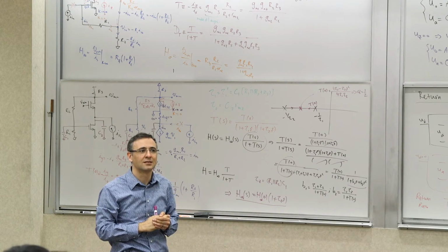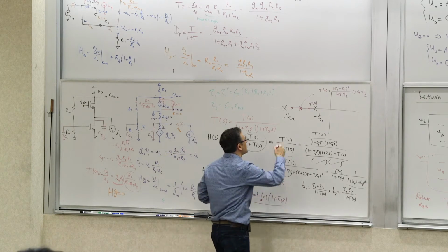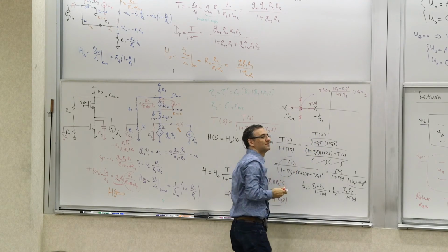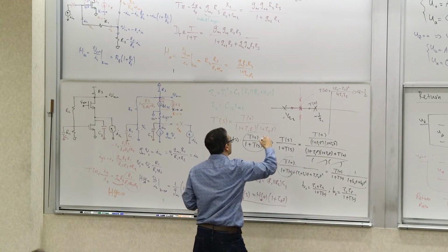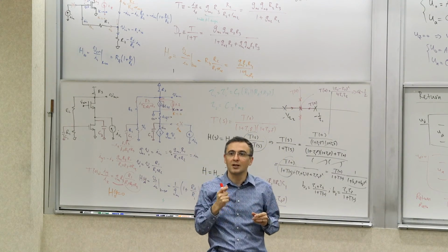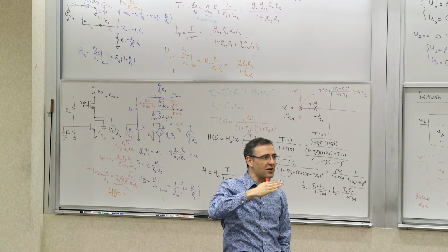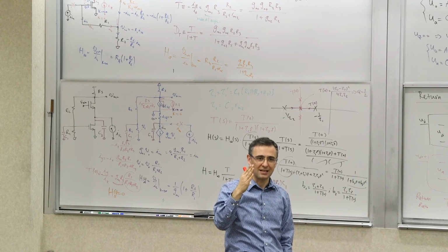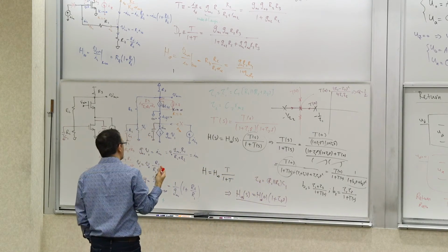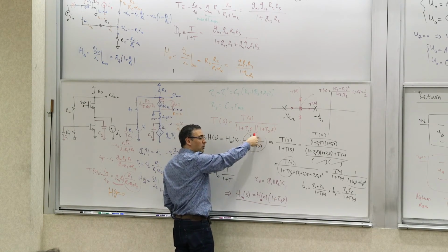So what happens after that? They split into a pair of complex conjugate poles, right? So they would go like that, and they will keep going as you increase T0. The system becomes progressively more and more underdamped, because now your zeta, your damping factor, is decreasing, and your quality factor is increasing. So you can imagine that this determines the response of the system. We are looking at the poles of this guy.